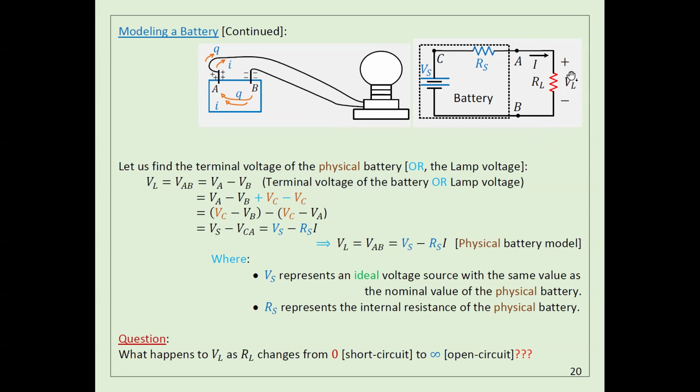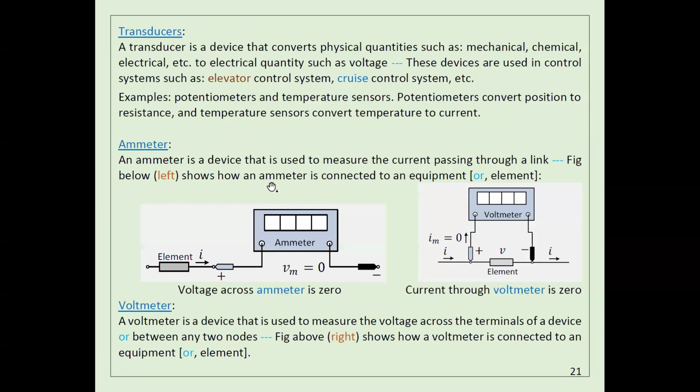Again, usually if this resistance is high, you can consider this one like a short circuit. So if you have a high resistance in series with a small resistance, usually we can ignore the small one, and actually most of the voltage will be across the high one. Anyway, any questions? Okay.